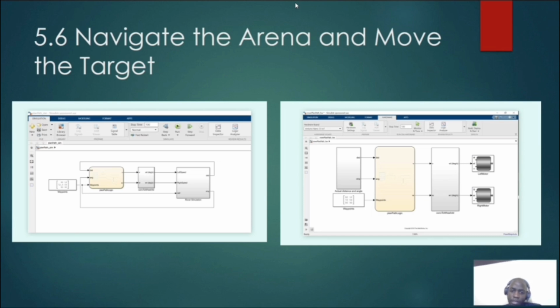To get the crucial localization data onto the robot, we use Wi-Fi communication. Our MATLAB script runs on the computer continuously, processing the webcam feed, and sends the calculated X, Y, and theta position data wirelessly to the rover. Our Simulink model runs on the Arduino, and the Wi-Fi receive block listens for data on a specific IP port configured to receive three elements, double vectors representing the position.